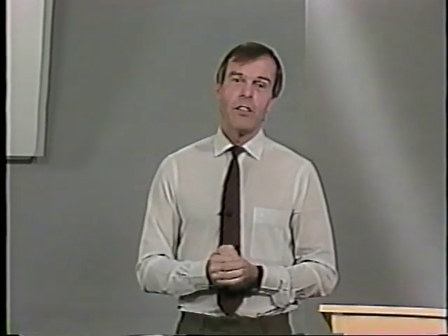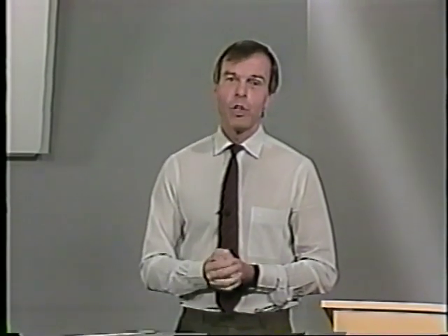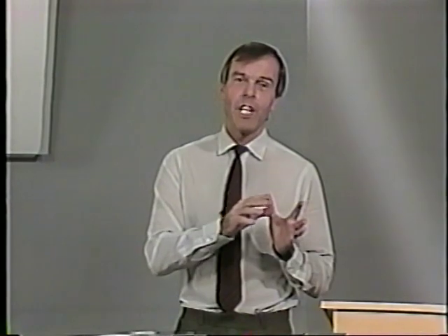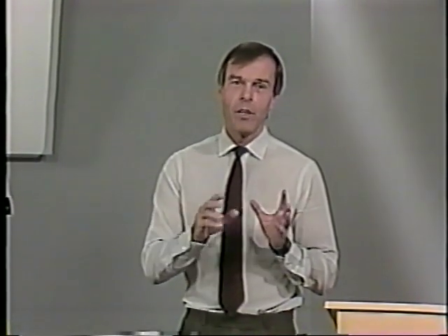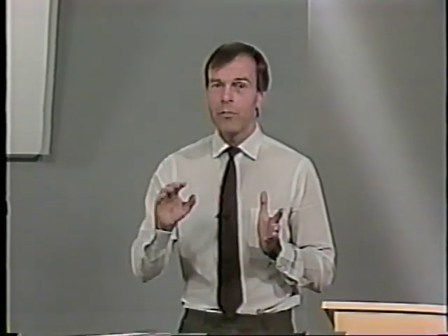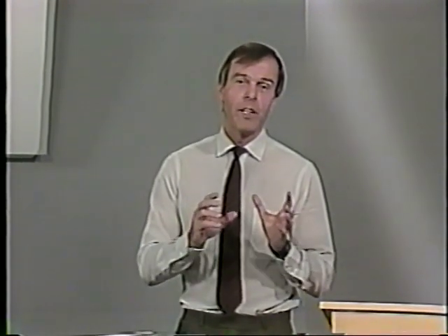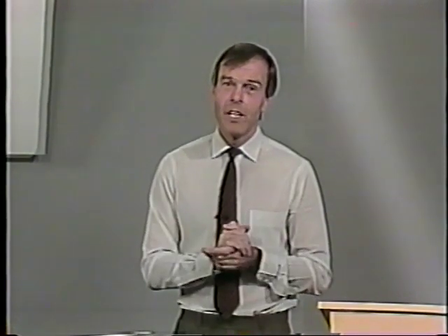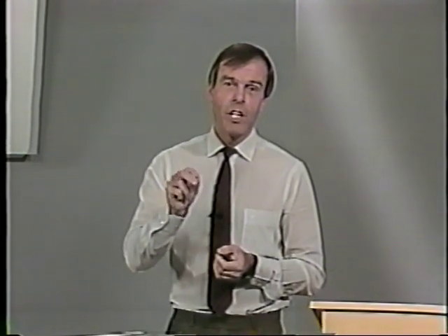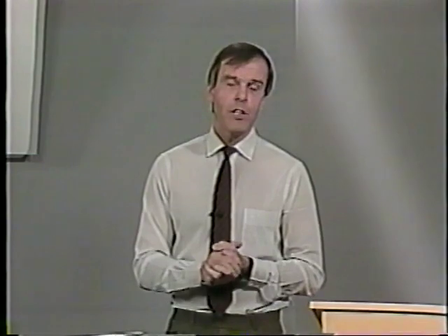In my textbook, actually, I have a little note, a footnote, that you might also look at in the beginning of chapter 6, where I discuss this principle of virtual work, that one way to look at it is that you see the body in front of yourself moving through the stationary coordinate frame. Once again, the Cartesian coordinate frame is stationary. You see the body move through that coordinate frame, and there's somebody standing taking a picture. And that picture is taken at time t plus delta t. And now you have a picture, and you apply the principle of virtual work to that particular configuration which has been captured in that picture. That's perhaps one way to look at it, at least one way that I like to look at it.